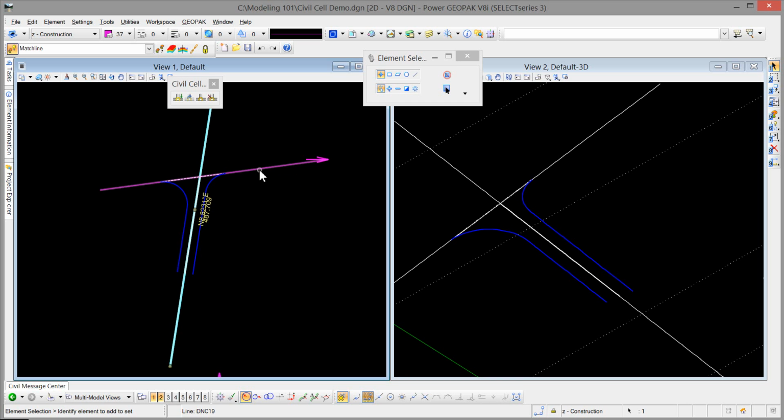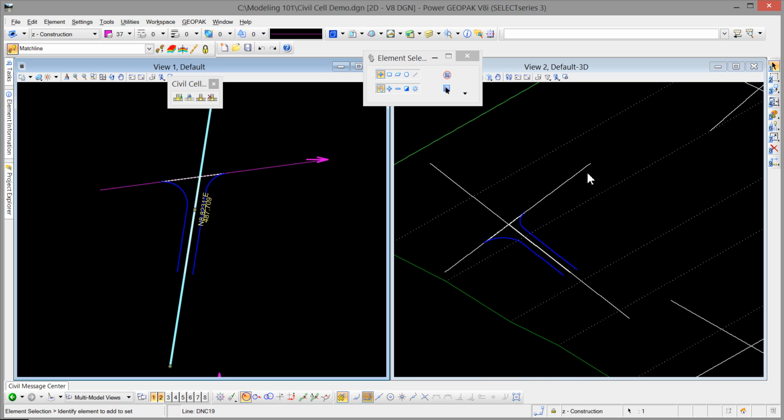And you may still, for whatever reason, have a placement reference line that is 1,000 feet long, but they only put a profile on it of 100 feet. And so they get to a certain point and things will start failing, and they couldn't understand why. That's why having your model open all the time is really important, because you need to see, have I moved off of where I have profile information?